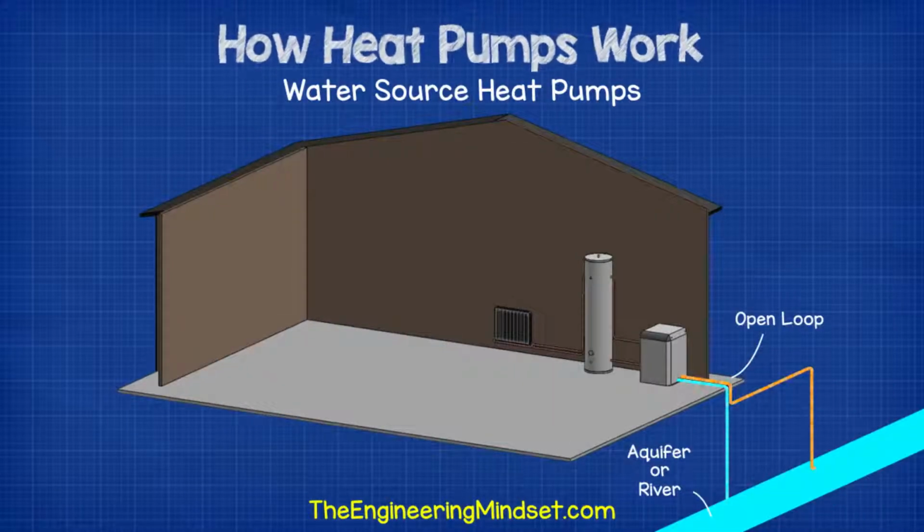In an open loop type, the water is pulled in via a pump and sent directly to the heat exchanger. The heat exchanger then pulls the thermal energy out of the water, or it dumps the unwanted heat into the water. The water then passes through the heat exchanger and returns to the source some distance apart.